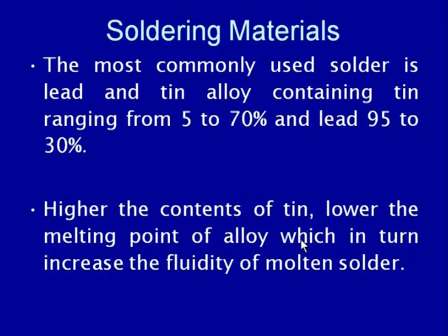The higher content of the tin lowers the melting point of the alloy, which in turn increases the fluidity of the molten metal. So, the low tin solders will be melting at a lower temperature, but at the same time they will be offering lower strengths also.